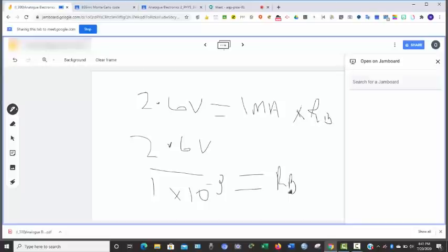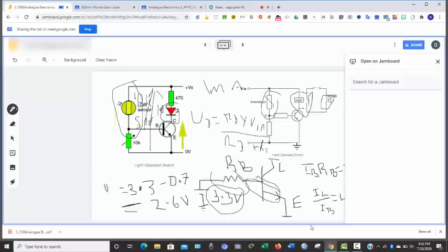That will give us 2.6 kilo ohm, and the closest resistor value under the standard scale that is close to this is 2.7 kilo ohm. So this, for me not to damage this transistor, I will need to put 2.7 kilo ohms at this place.